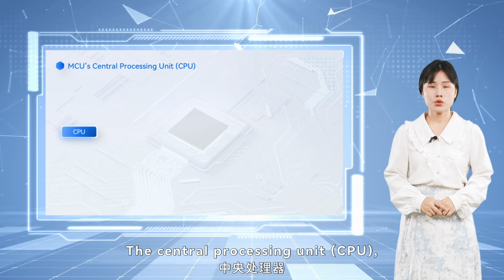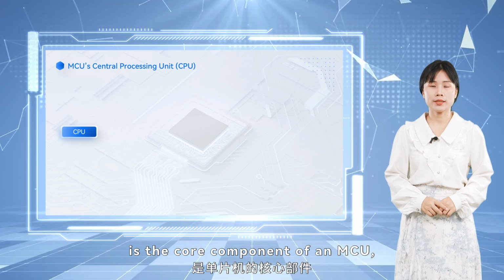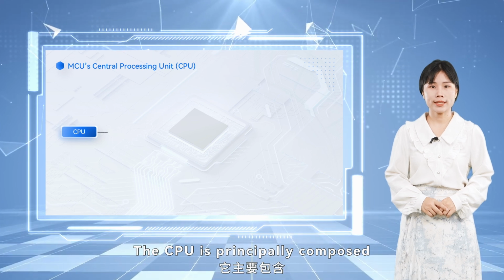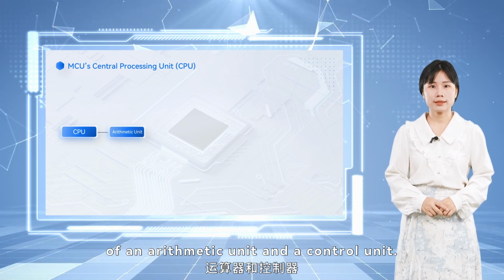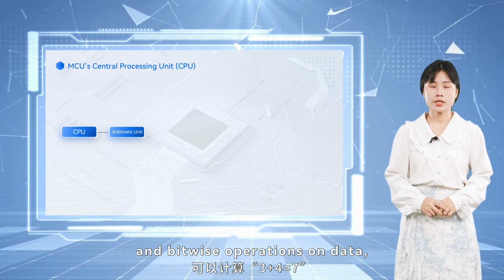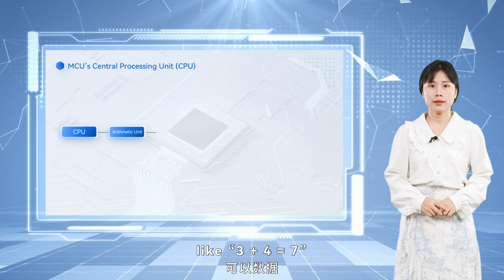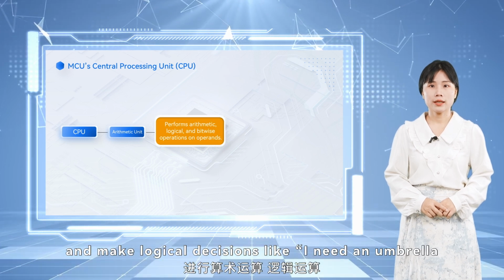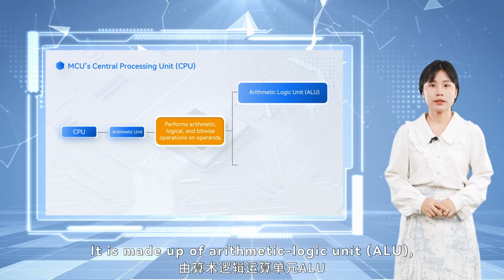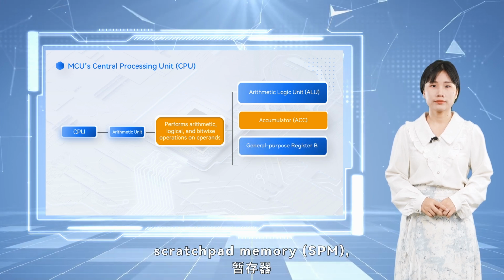The Central Processing Unit, CPU, also known as the microprocessor, is the core component of an MCU, the control and command center of the MCU. The CPU is principally composed of an arithmetic unit and a control unit. The arithmetic unit performs arithmetic, logical, and bitwise operations on data, akin to how our human brains handle mathematical calculations like 3 + 4 = 7 and make logical decisions like I need an umbrella as it's going to rain today. It is made up of arithmetic logic unit, ALU, accumulator A, general purpose register B, scratchpad memory, SPM, program status word, PSW, etc.